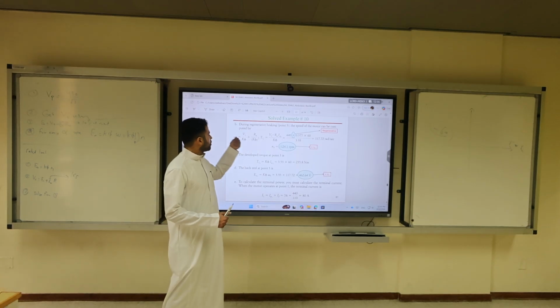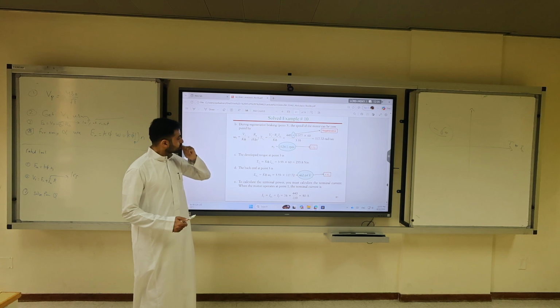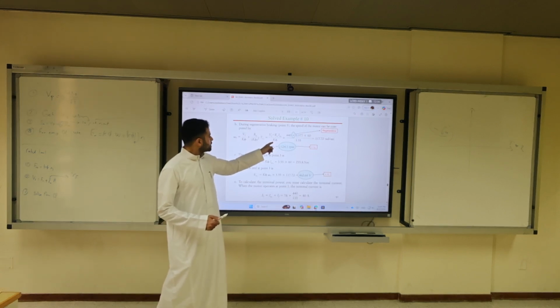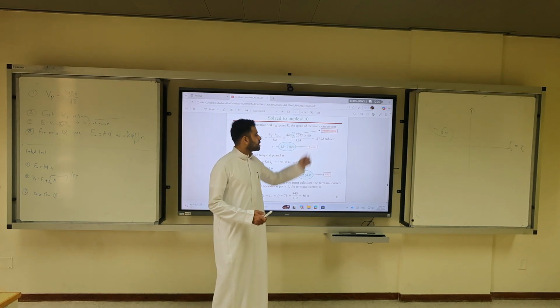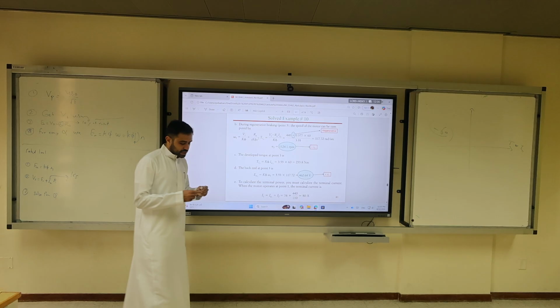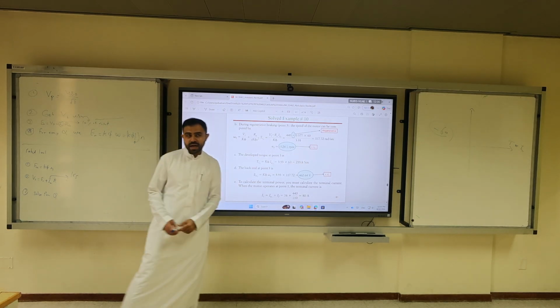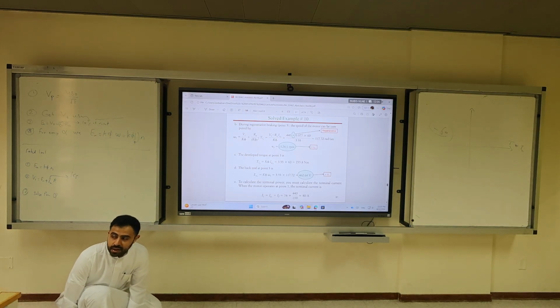Now, you can use this equation. Make sure to include this equation. It's Vt minus RA IA over the flux, K phi. So the speed will be 117 radians per second, and it is higher than the no-load speed. Why is it higher? Because we are in the regenerative braking. Your EV is going down the hill.